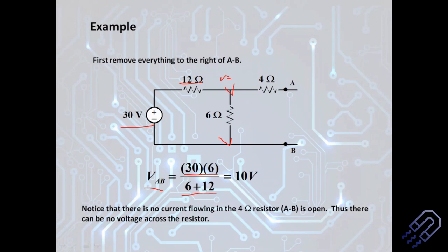You can do it this way, or you can simply find out V minus IR, where R is nothing but 12 ohm, and V would be nothing but 30 volt, and R is already there, but I you have to calculate. So you can do it that way also, but this is the better way because this is easier. This method you might have used.